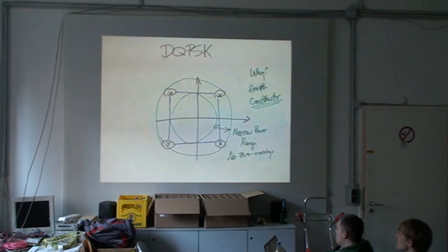Crest factor. Dieter talked about crest factor earlier with UMTS. Crest factor is the ratio between the mean power level and the peak power level that can be produced by your modulation. By keeping signals out of the origin, by trying to constrain the signal to a circular space in this IQ space, you minimize crest factor. So a signal with crest factor of 1 would be a perfect circle, just a clean circle in this space, and we'll see some examples of that.